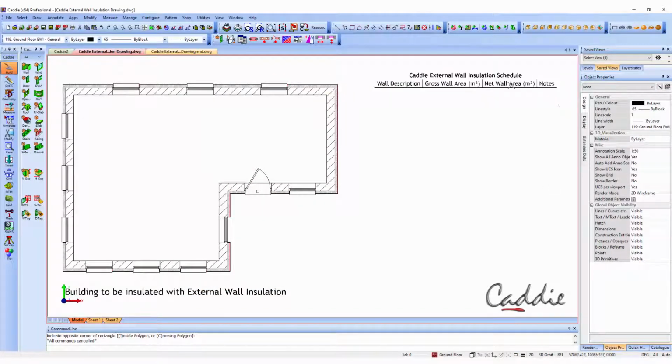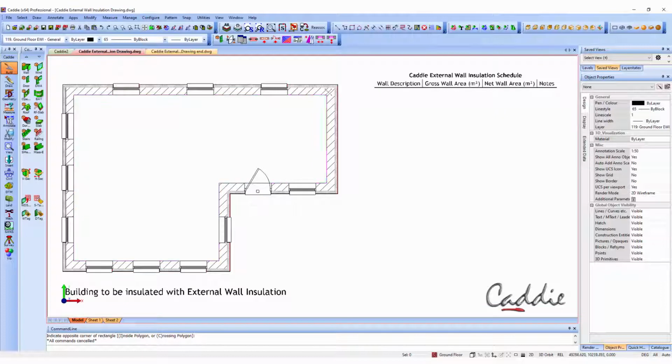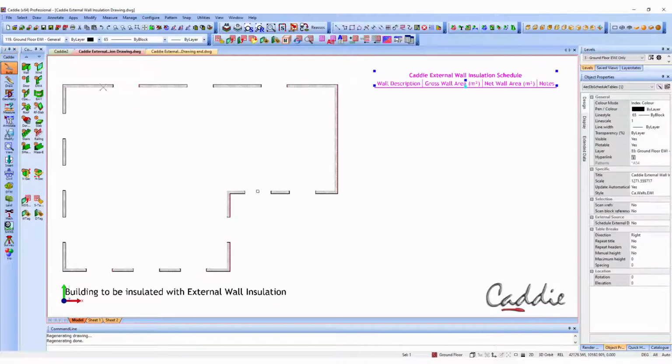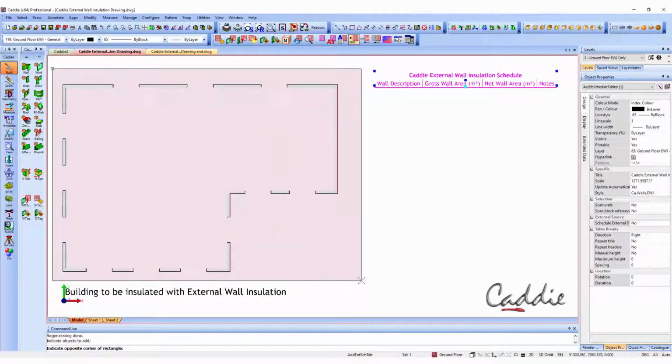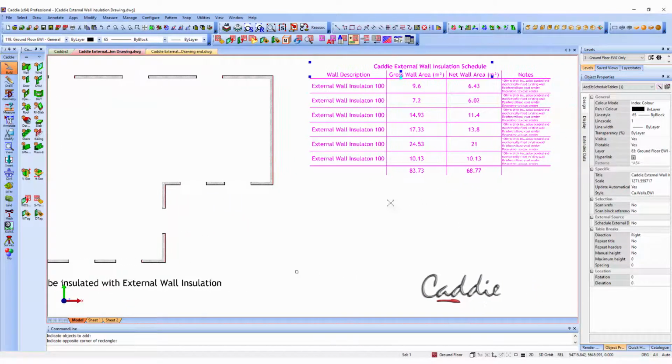And going back to our plan, the one thing that we have at the top then is the schedule. So to add the walls onto our schedule, so it'll list them down below it, what we need to do to just mean that we don't include all of the existing walls is just choose purely the new work. So we'll select our schedule style, we'll add in from the context toolbar there, the dynamic toolbar, we'll add in the walls, and we see that we have the full listing there.